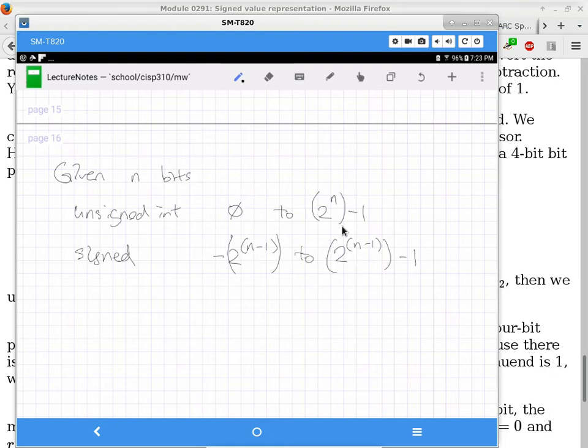In other words, you simulate the whole thing using a PC because it's easier to debug on the PC. You can just use GDB or use the GUI debugging ability of Code::Blocks or whatever. And then the program would be ported to run on an Arduino type of processor, because that's where the robot is. The robot is implemented using a much weaker processor, like the ones used on Arduino boards.